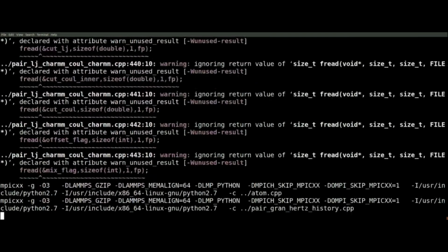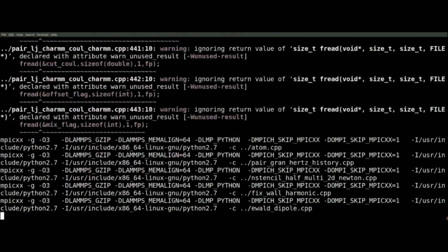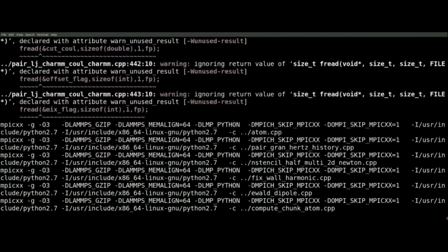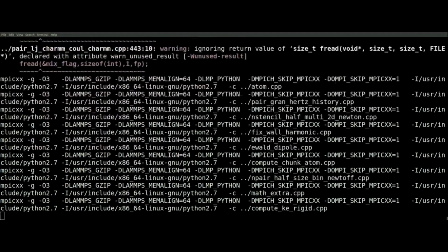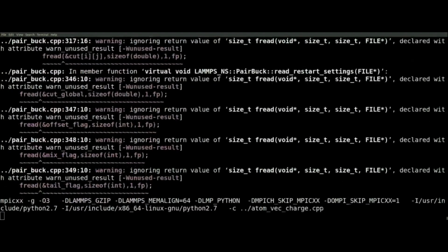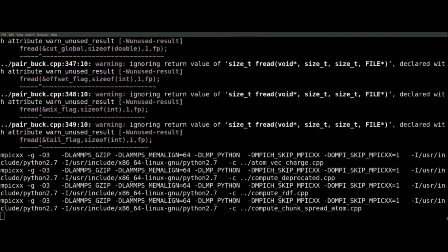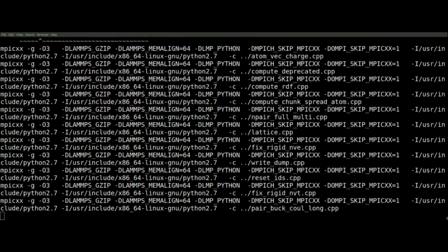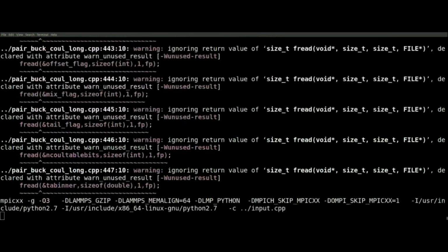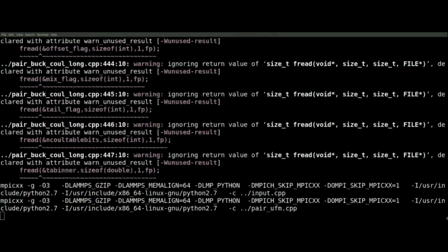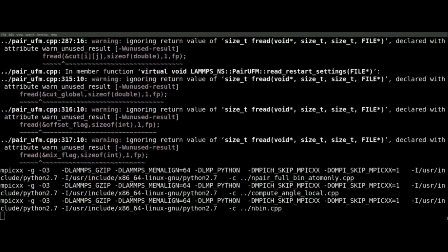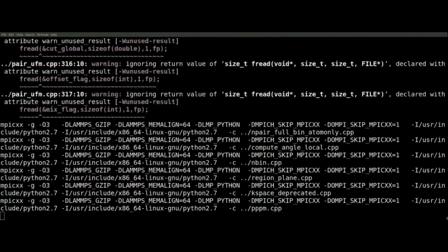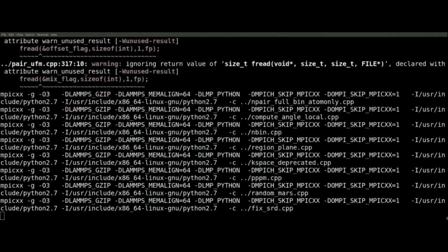And after the break, I will be talking a bit more about some of the harder to make packages, things like Voronoi. I'll also be talking a bit about compiling for GPUs and briefly about how you can actually hack some of the LAMMPS code to maybe make force fields or fixes or computes that don't currently exist, where you can go to find help for that, and where you can go also to let the LAMMPS community know about this.